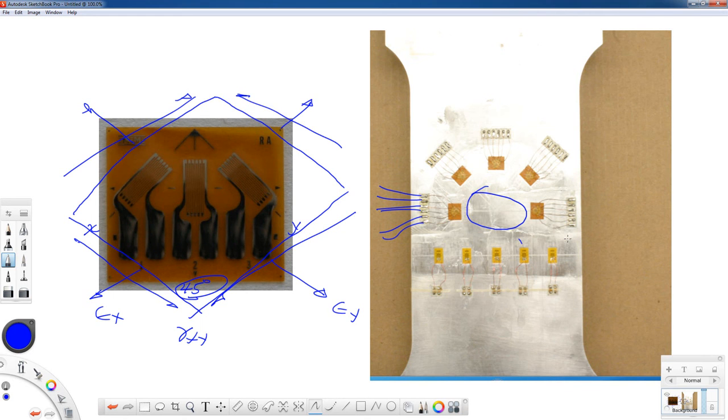You can spray a coating on a component, and you can see how the thickness of the coating and the optical properties of the coating change when the material underneath of it is stretched out. Those are called full field strain techniques. Those are a little bit beyond what we're going to talk about in this class, but you may take a class, one that I teach is experimental stress analysis, where we get into these different types of strain measurement techniques.